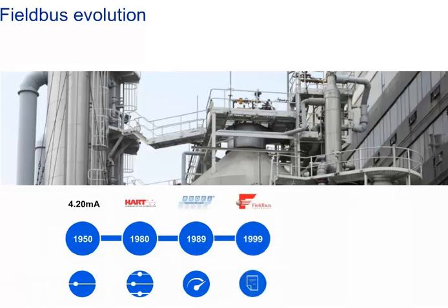In 1999, a second digital bus was launched, Foundation Fieldbus, developed by the US-based company Emerson. Although both bus technologies share exactly the same physics, their protocols are substantially different. In 2006, Profinet was invented, a new Profibus technology additionally transmitting the Ethernet protocol via the Profibus.